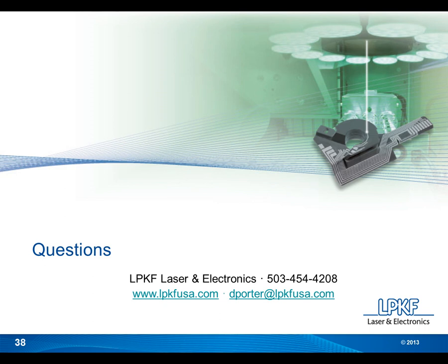The most normal, most conventional, most common way to do it is to actually mold a through hole, and you mold this with a conical entry point. So it's a cone going through the plastic, and you can have that going from both sides because you can structure from both sides. Then you have an angled surface to that hole, and you can activate that with the laser, and that does plate through, so you get a full through connection with that.